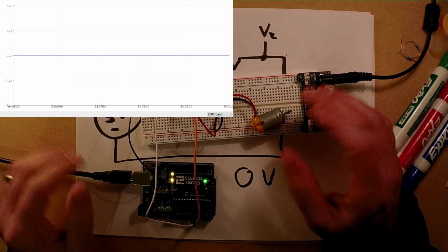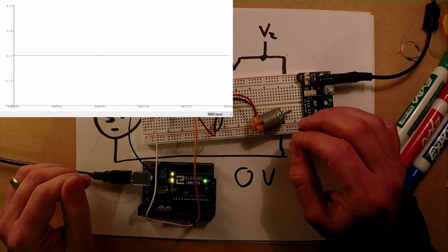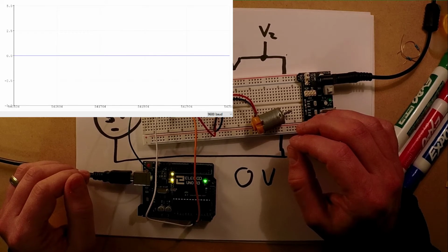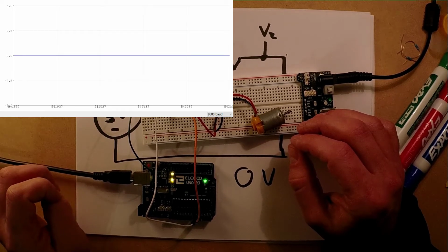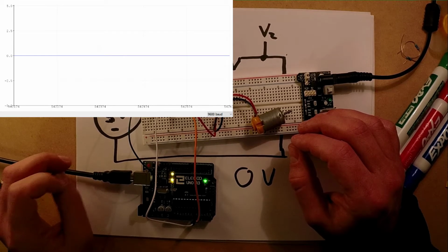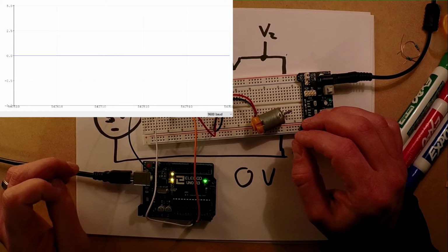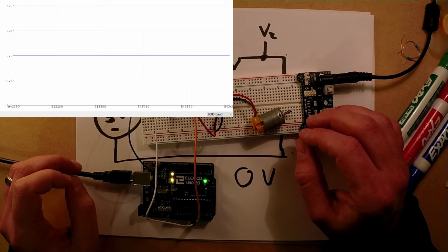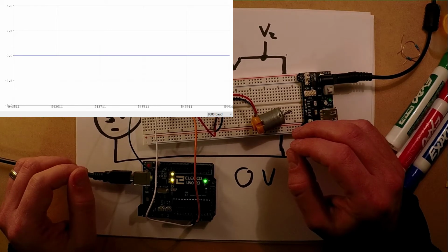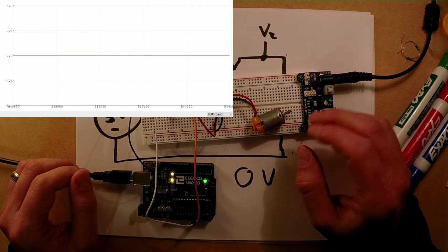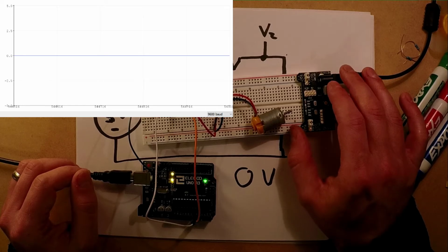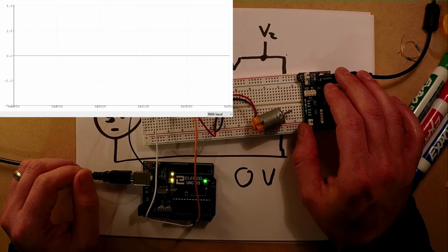If we have a big starter motor in a car that runs off 12 volts, it's not going to run off of just a small benchtop 12 volt power supply because it's a big high power motor. It needs a ton of amps at 12 volts to be able to turn itself over. So we need to consider how many amps our load is going to take before we pick out a power supply. So something to keep in mind as you work on this activity.